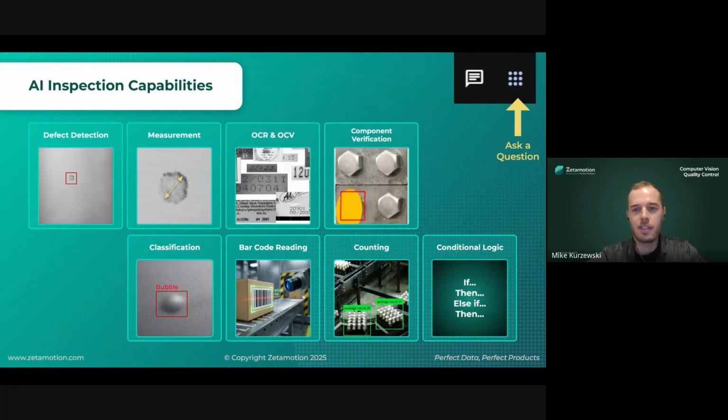All of these things can start stacking up into what can be conditional logic. And it can also be something that you account for in the hardware. So what to do with the product if it fails. Like if it fails, then move the product off the line, or have some sort of sorting station that sorts the failed and passed products out on the production line.